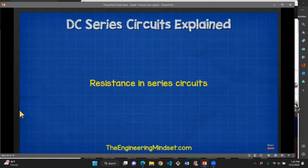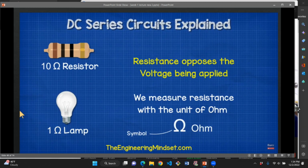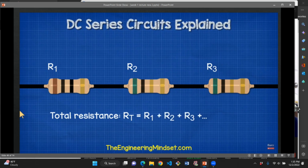Resistance in series circuits. Each component will have a certain resistance. The resistance opposes the voltage being applied. We measure resistance in a unit of ohms. In series circuits, we find the total resistance for the circuit by simply adding together all the resistances. We label each resistor with a capital R and number them R1, R2, R3, etc. The total resistance is shown with a capital letter R and a subscript T, which represents the resistance total. To calculate the total resistance of a series circuit is super easy. We simply add together the resistance value of each resistor.